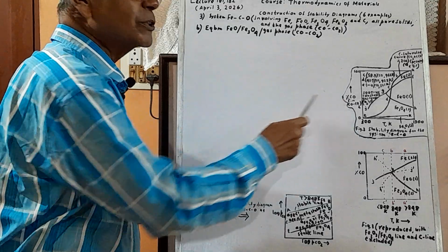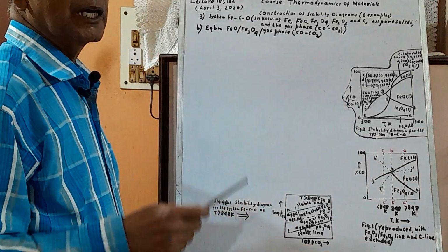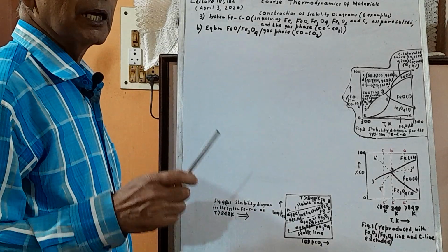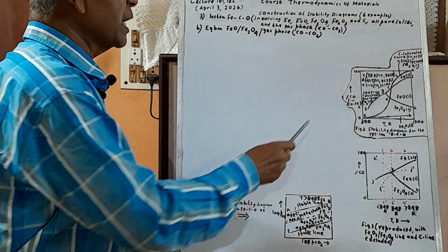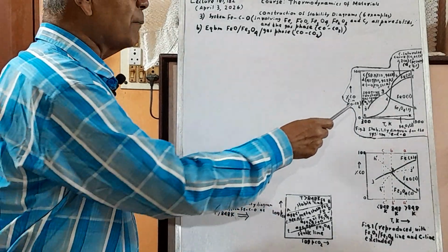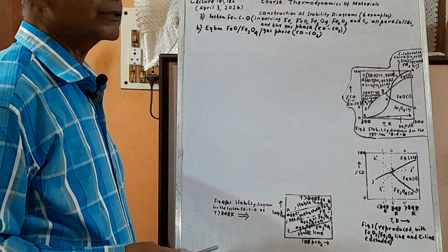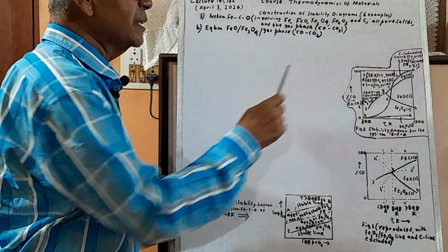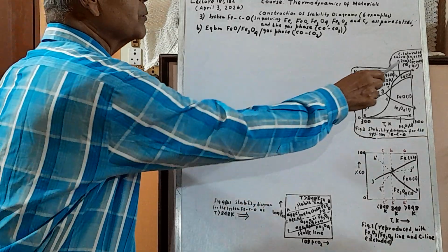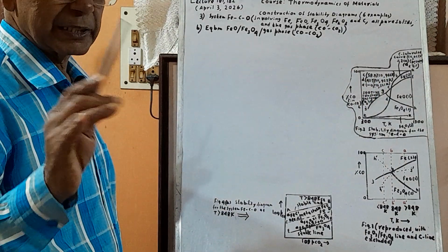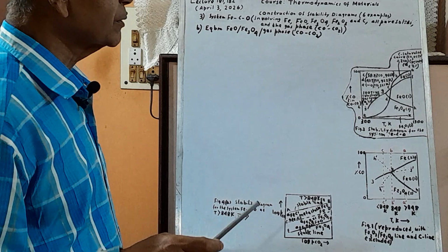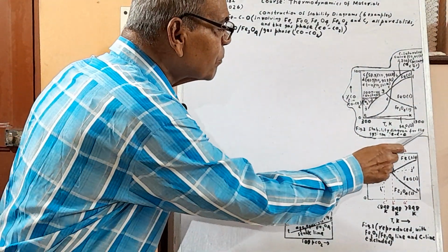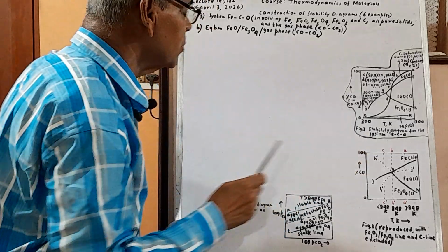This is only the CO2 content. So if you have infiltration of nitrogen, or the presence of nitrogen in the gas phase, then you have to apply it suitably. You have to exclude nitrogen and find the percentage CO. Total pressure is 1. This is a critical thing. It is complicated, but no problem. So this is called the stability diagram for the system Fe-C-O.